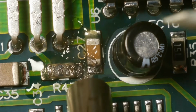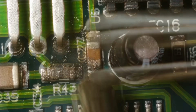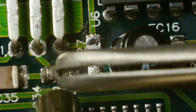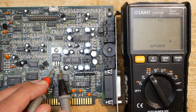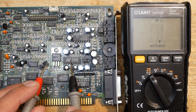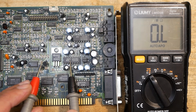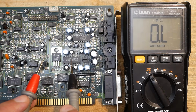For me, it looks like the most mysterious case. First of all, let's remove the burned parts and see if the short disappears. The best scenario would be if the small decoupling SMD capacitor is half shorted. Then it could be an easy fix. Well, without the burned SMD parts, we are still getting 9 ohms on the voltage regulator. The regulator usually provides 9 volts to the amplifier, which means that probably either the voltage regulator or the amplifier is dead. Maybe even both.